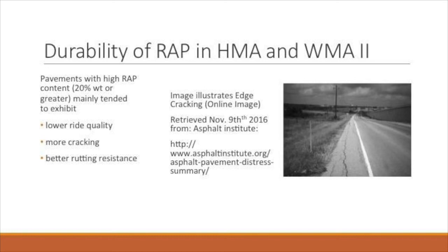The typical durability issues with high RAP pavements are more cracking, resulting in a shorter serviceable life. It was also shown that using RAP can lead to having increased rutting resistance.